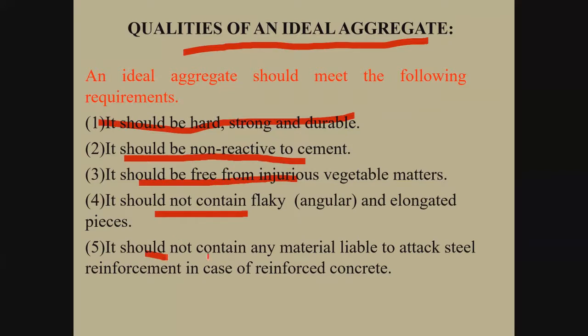Then concrete aggregate should not contain any material liable to attack steel reinforcement. If we are preparing concrete for reinforced concrete RCC purposes, and there are some impurities present inside the aggregates which will attack the steel, then the resultant RCC will not be stable, and there will be a lot of problems with the reinforced concrete. So these are a few parameters which we must keep in mind before selecting a type of aggregate for our concrete mixture.